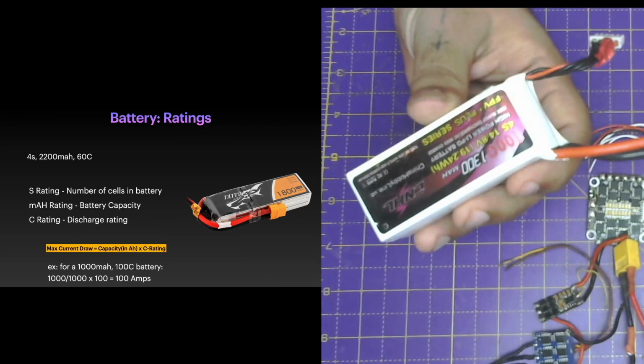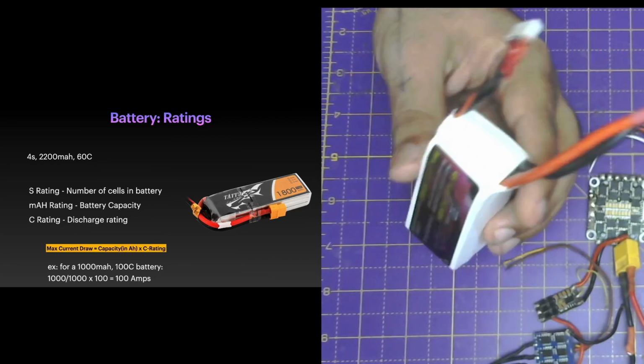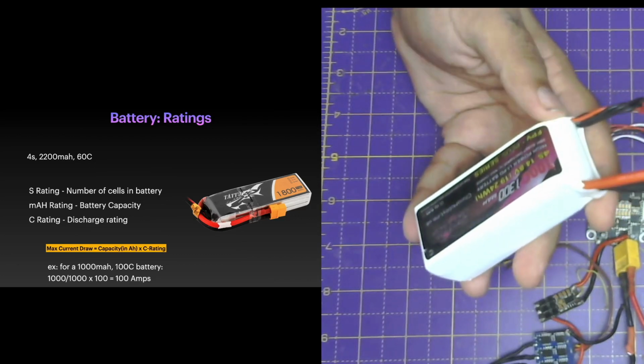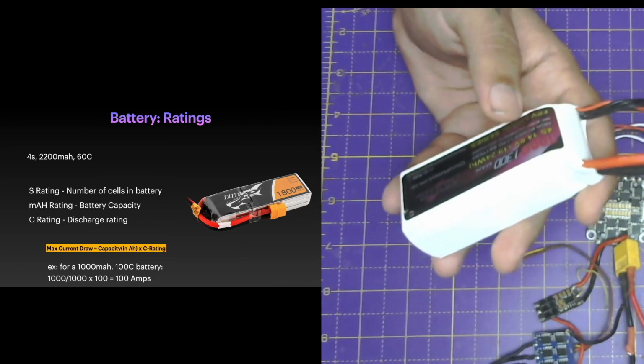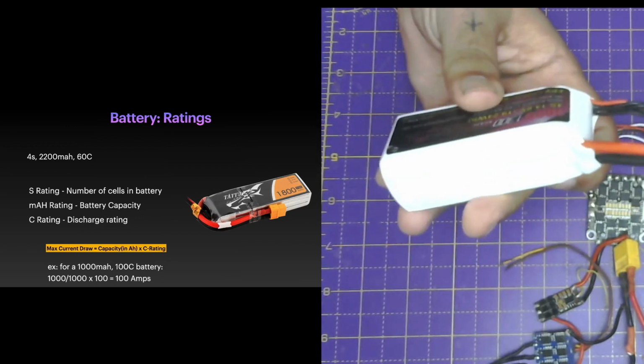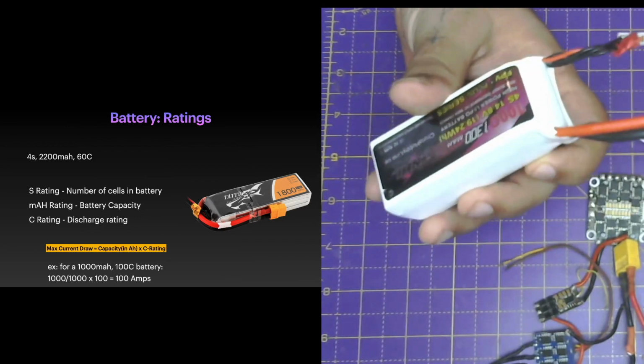And even when you are charging and discharging the battery, make sure to never discharge it beyond a certain limit. Make sure to never discharge the battery beyond 3.6 volt per cell. Otherwise the cell will be damaged forever and you cannot recover the cell.